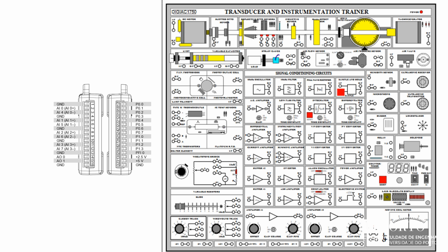This model is going to be connected to the bench so we can control using the LabVIEW application. So first of all, we need to connect the ground from the model to the bench. So voltage reference are the same. Then we're going to use an amplifier, and this is necessary because the National Instruments model has an analog output that ranges from 0 to 5 volts. So we will need to amplify it.